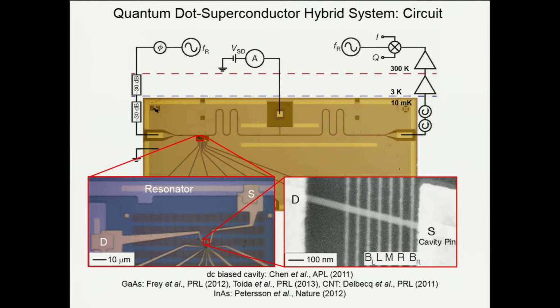And the way that we're doing that is by directly connecting our quantum dot device to the two different sides of the capacitor in this LC circuit. Therefore, this entire voltage is dropped across this nanowire, over about a 500 nanometer length scale. It gives us a really large electric field in the region where our dot sits. And this is important to get the charge to actually talk to the microwave frequency photon. This was worked out by Carl Peterson, a former postdoc in the group.